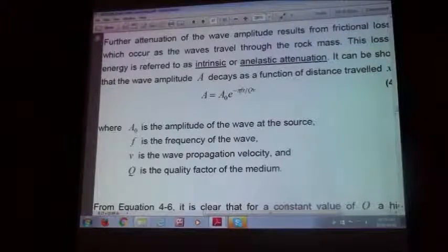Of course, you also have to look at the location of your sensor relative to the source. If you've got a ray path that goes through an excavation, your energy will still leak around it, and you'll still get an arrival there, but it will be very much delayed, and it will be distorted. So as you analyze, you'll get a quick and dirty, fast location, but when you want your accurate location, you have to consider all your arrivals, and you'll discard a whole lot of them because they would have been in the shadow of an excavation, or the ray paths would have gone through a fractured zone, for example.